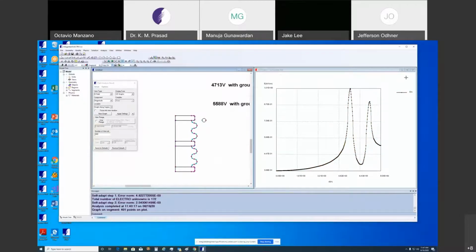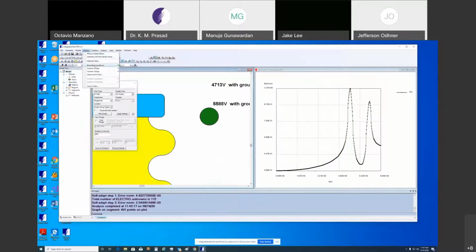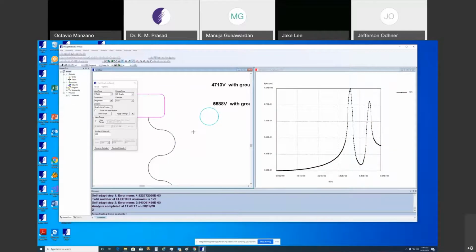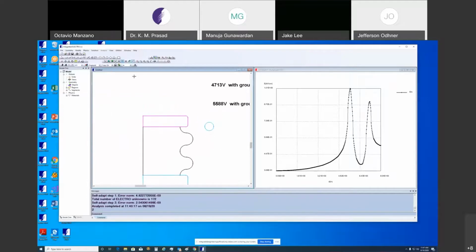So you can calculate the electric fields at any place you like. Okay. Now the corona ring at this place, let me see here, physics. What kind of boundary current? We have used 10,000 volts here. Now, this time I'm not using 10,000 volts, I'm applying a floating boundary condition. Okay, now let me solve this problem again.